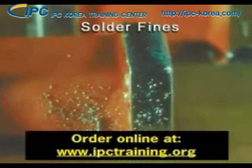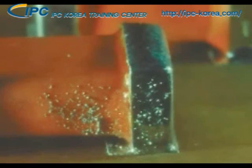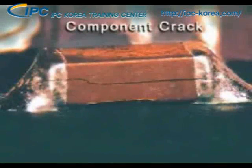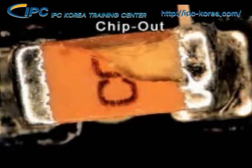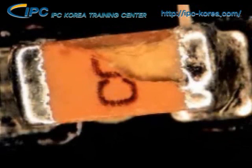Solder fines are small balls of solder paste that have splattered around the connection during the solder reflow process. This condition is considered a defect when the solder is not encapsulated or attached to a metal surface, or the solder fines violate minimum electrical clearance. Any significant cracks or stress fractures in the component body are also considered a defect, as well as any nick or chip out that exposes the electrodes or resistive elements. Again, that's because the electronic signal will be interrupted.